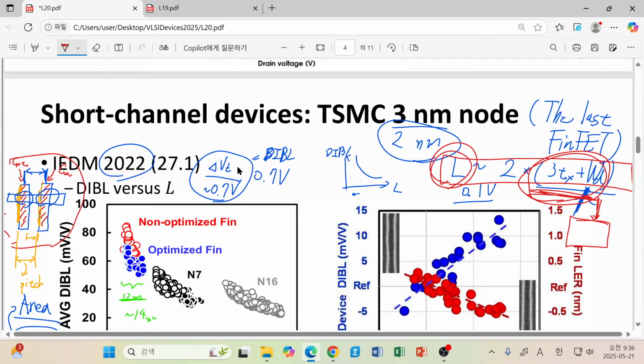So that is the real issue occurring every day in the industry, and we are currently spending tremendous research and development effort to build new technology. It is very interesting that all kinds of this complicated effort are related to quite a simple argument. In order to suppress short channel effect, we must have a thin system. Why?